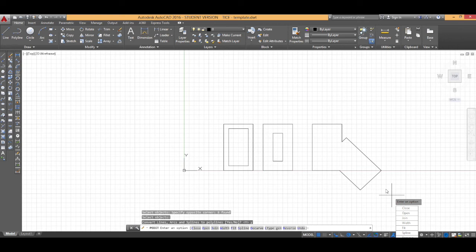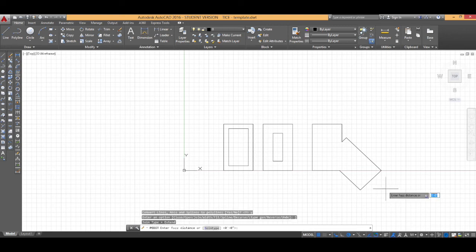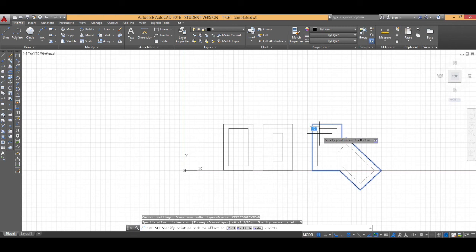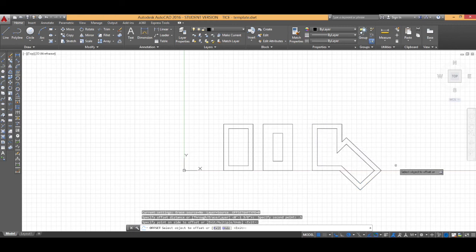It'll then ask what you want to do with these new polyline segments. We're going to J or join them together, and at a distance of 0. You can click Escape to exit the command. Now, our individual line segments are one single line in this dynamic shape. Then, apply the offset command at 0.5 or half an inch and select the object.